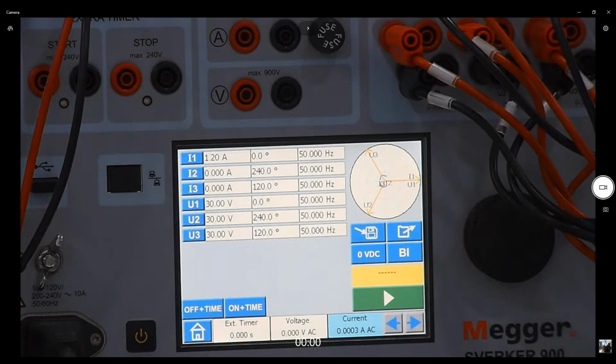Now, if I want to do testing for the phase angles, or even before starting the phase angle, if I want to do testing for the pickup and timing test, since I see a lot of requests indicating just that, especially from people who are working with maintenance. I need to make sure my phase angle is within my operating region.